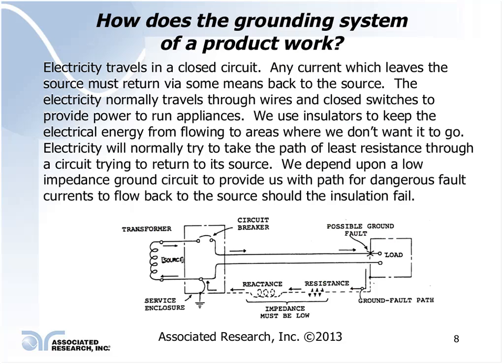My brother came home. He enlisted in the Navy, and he was about 12 years older than I am, and I remember him attaching a ground wire to the refrigerator, and that basically eliminated the shock hazard. Once the frame of the refrigerator was tied back to ground, all that current was safely routed back to ground, and essentially eliminated the shock hazard.